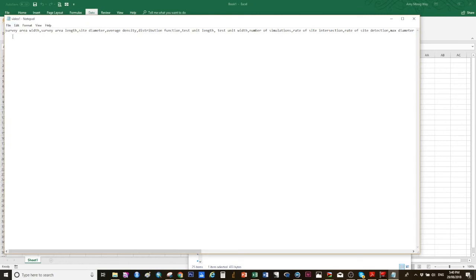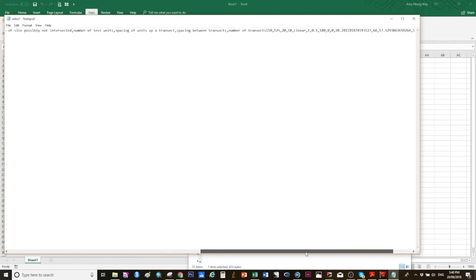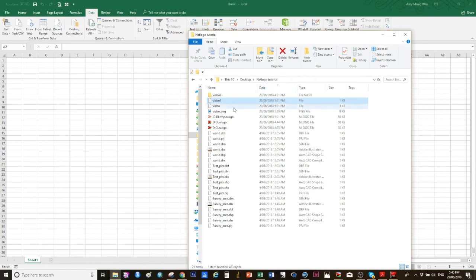So what we've got here is I've opened the file that contained the grid parameters and the simulation results. You can see we've got a long list of headings, so these are just the things that you've exported, and then the actual results of those follow in the list. I have noticed that Excel sometimes won't recognize this file automatically without putting a .txt at the end. So all I'm going to do is rename it where I stored it with an extra file extension .txt